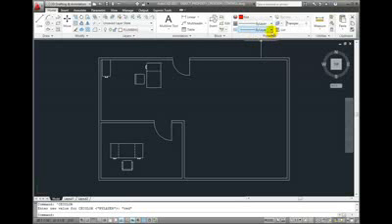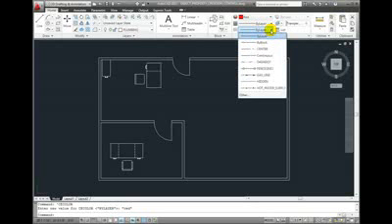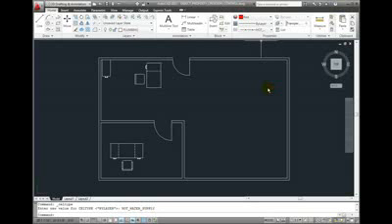I'm also going to come down here and change the line type. Let's change the line type to hot water supply. So I changed two properties. Any new object that I create will be created on the plumbing layer, but using these explicit properties. Any new geometry that I create will be created with the color red and with the hot water line type.